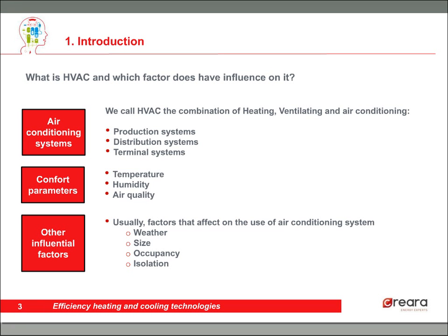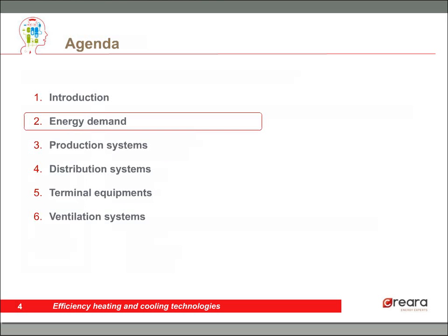And that is because the thermal exchange in the chiller is going to happen in France at 20 to 25 degrees, and in Cordoba it is going to happen at 45 degrees. And that reduces a lot the energy performance of the chiller. So these parameters do affect the energy efficiency of not only chillers, but every producing system.